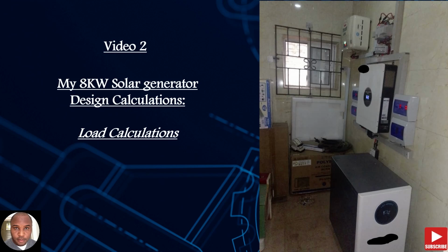For my own installation, I used 8 degrees, and the advantage of using that is, in Africa we have plenty of sun. Trust me, from 7 o'clock in the morning, when the sun is just coming out, I have already started generating power, because you get the full blast of the sun when it's almost flat, almost all through the day. Your solar panels will be producing electricity for you when you get your tilt angle correctly. So tilt angle, very, very important.